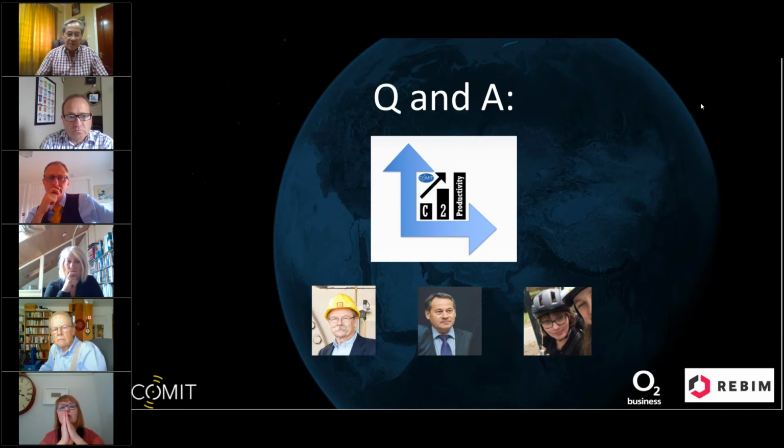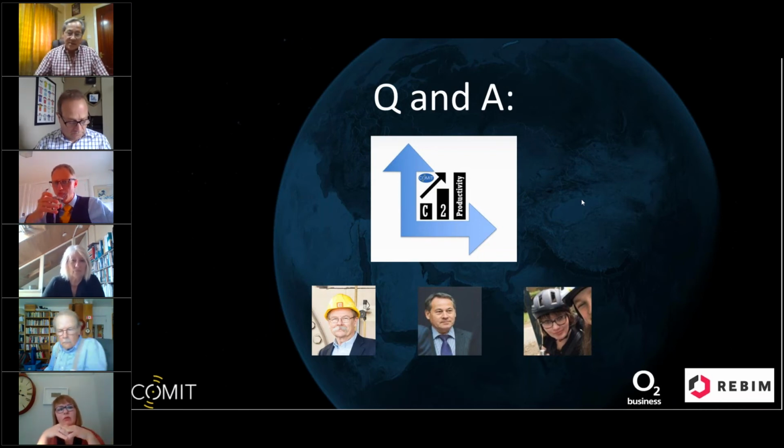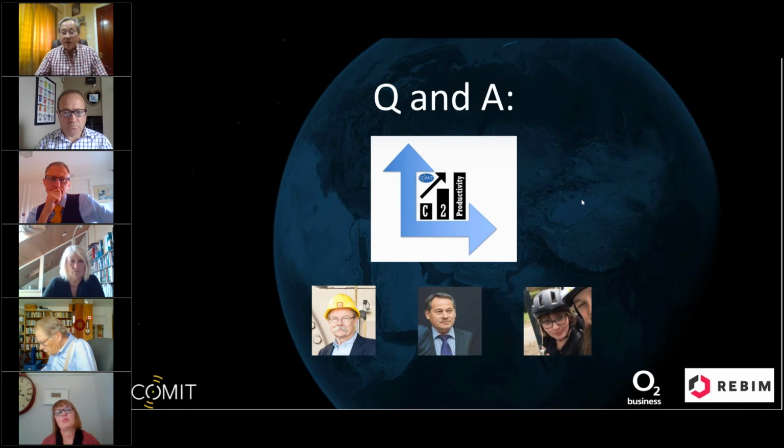I'd like to contribute to that, because yes, 3D data is absolutely essential. If you haven't got Z depths and you only know where a pipe is in plan, then there's still a good chance that you're liable to hit it. So new data going forward is recorded in 3D because of the technology that we have. But existing data, like Jeff says, is typically in 2D, fairly sketchy at best. However, we're still opening up trenches on that old network, and we should be getting Z depths.